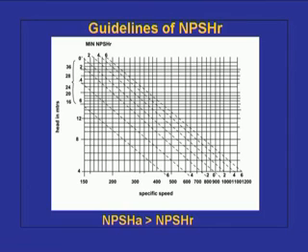The NPSH available can be easily determined using Bernoulli's equation, or the engineering Bernoulli's equation, between the sump water level and the suction side of the pump, accounting for the difference in the elevations and the energy loss in the suction pipe. So that NPSH A should be greater than NPSH required. Typical NPSH required curves are given in this figure for centrifugal flow pumps and mixed flow pumps.